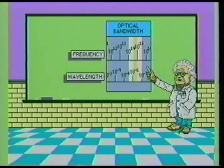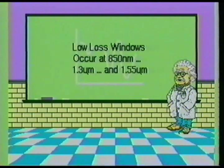The portion of the spectrum used for optical communication extends from the infrared to the ultraviolet wavelengths. Low-loss transmission windows were discovered at 850 nanometer, 1.3 micrometer, and 1.55 micrometer wavelengths. The longer wavelengths of 1.3 and 1.55 micrometers exhibited a typical attenuation of only 0.2 decibels per thousand meters of fiber.